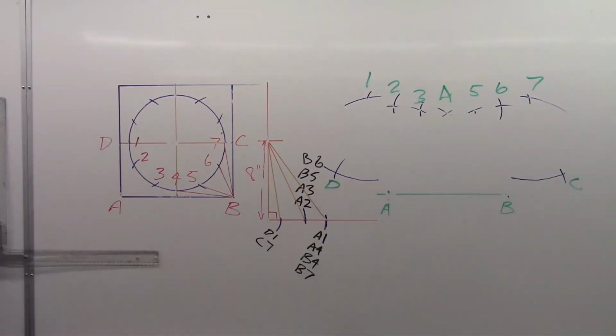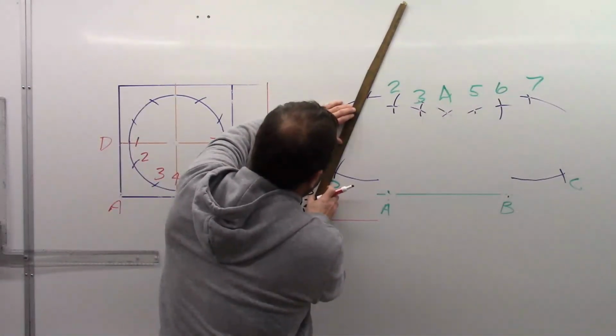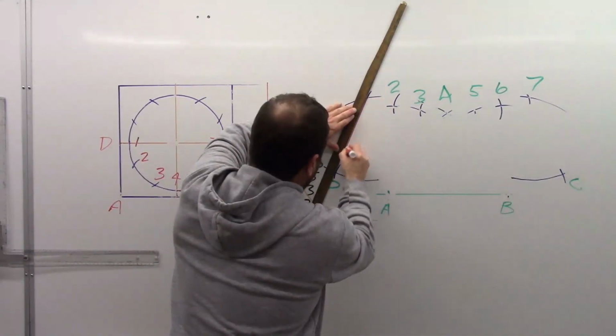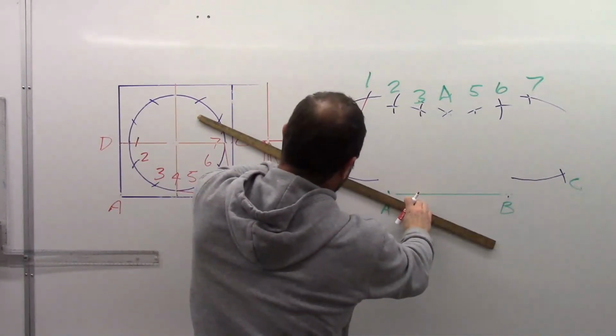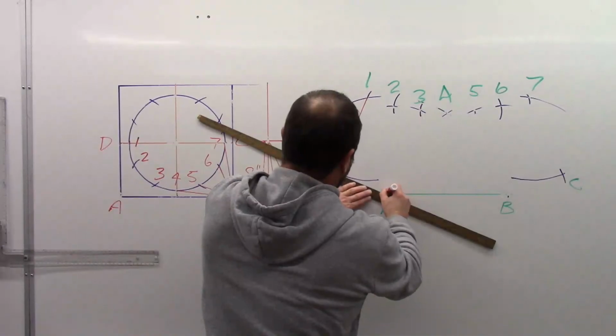We do have a way to check our pattern, and that's on what we refer to as the wing here. And that's this last triangle that we made. And the wing on a squared around will be a 90-degree corner.